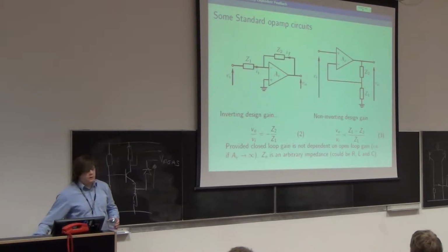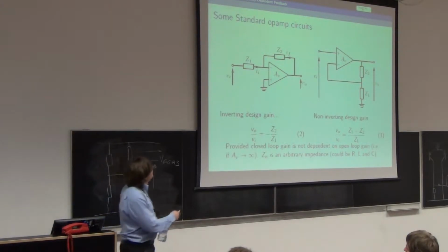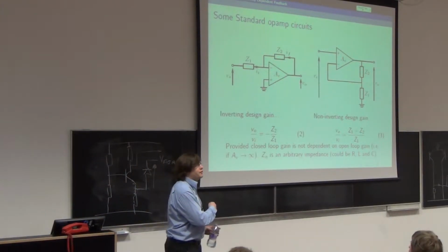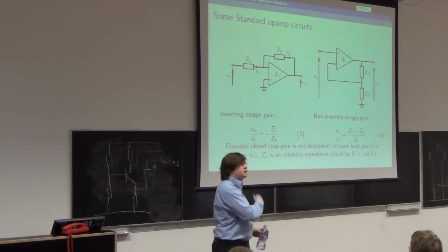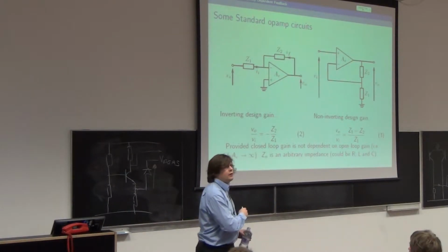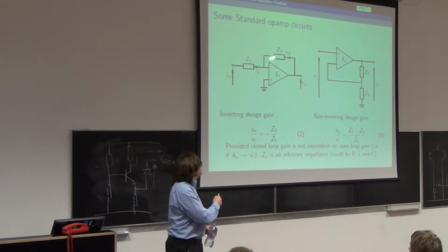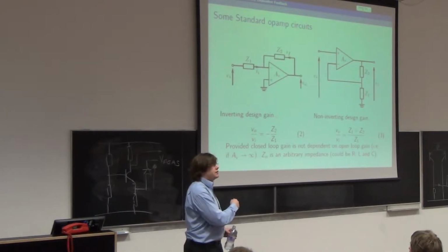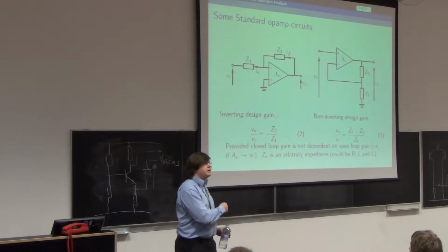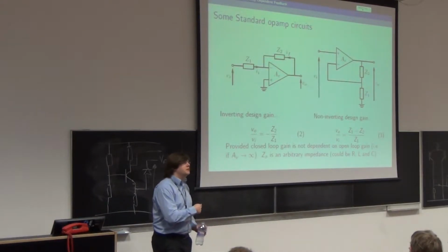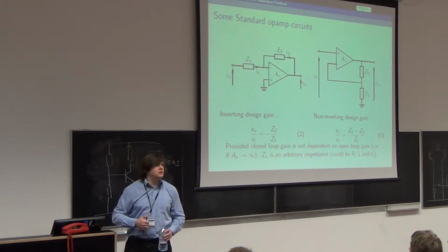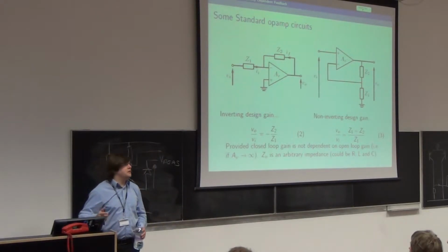Happy? In these situations I put AV in and I will make AV first order, as it was a few lectures back. If I had some capacitors here, if these weren't resistors, I would take away the AV and make it infinite open loop gain with no frequency dependence. Otherwise I'd end up in some second order situation, and I won't do any of that in this course.